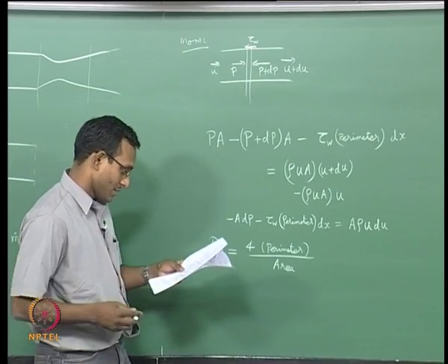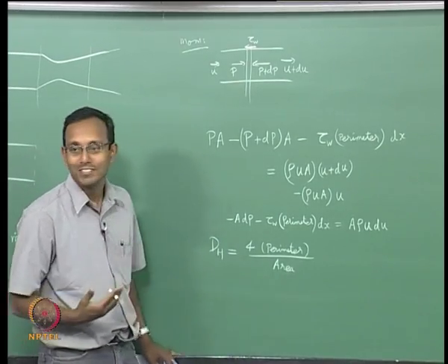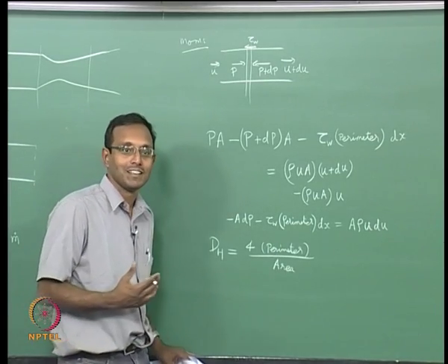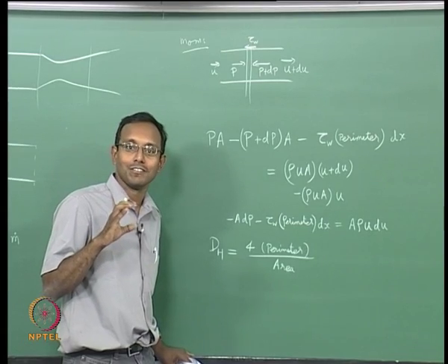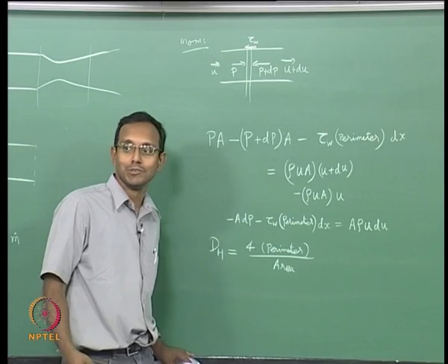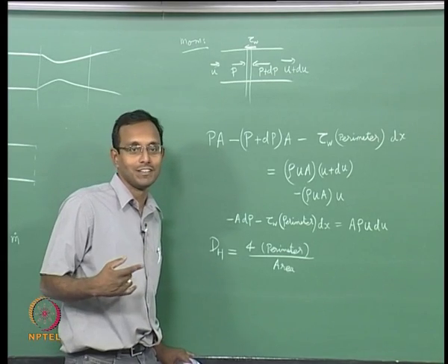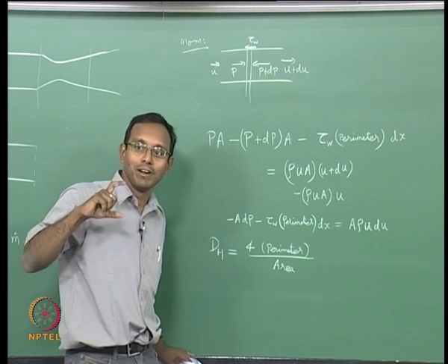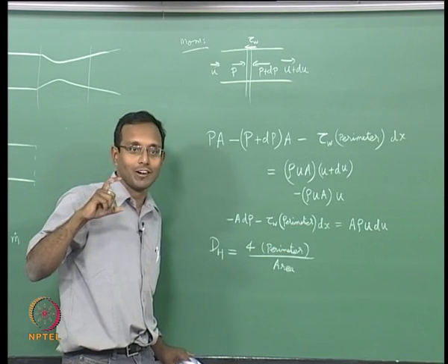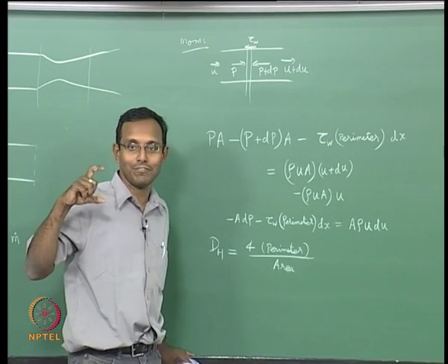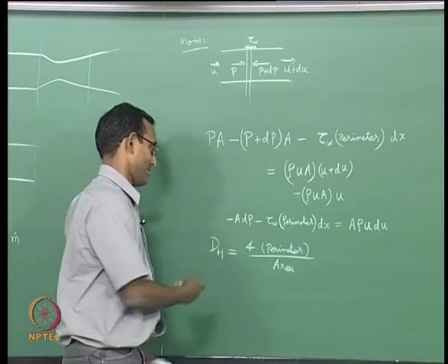Okay. How do we get to this 4? This is the engineering way of looking at things. Not all ducts will have a circular cross section. So engineers used this and finally found that if I use this formula, I will get the diameter for my circular duct naturally, and if it is a square duct, I will get the side of that square. Okay. Just see that directly.